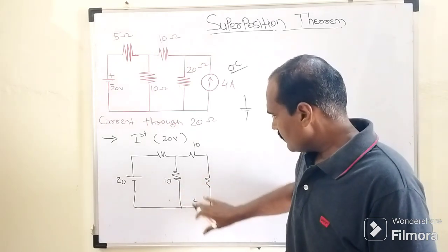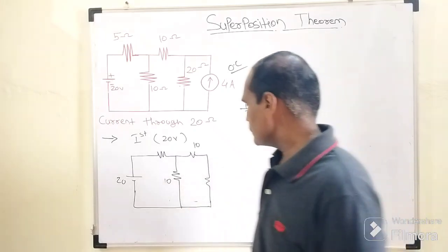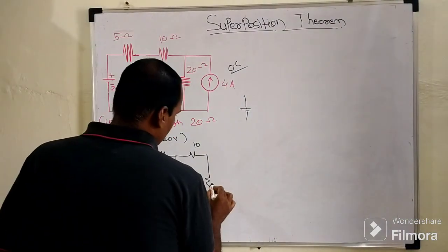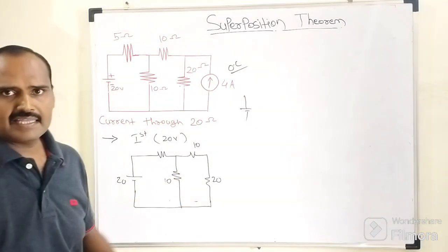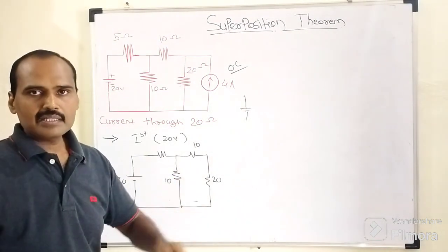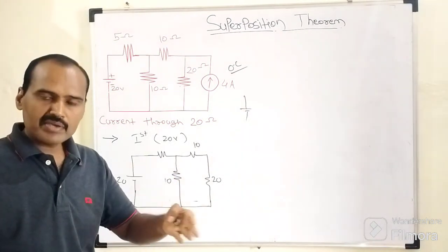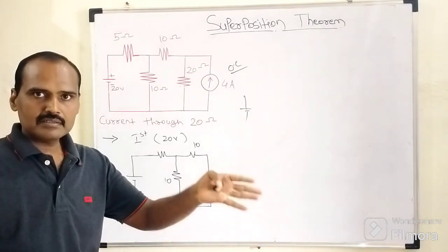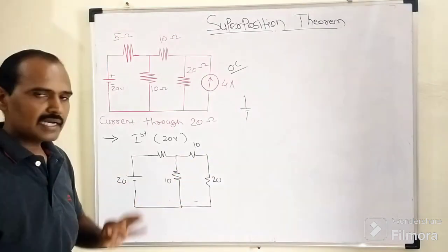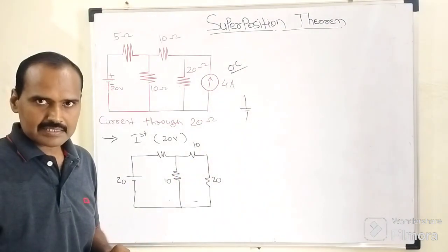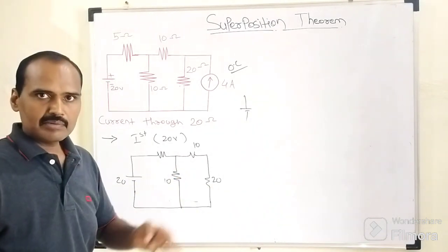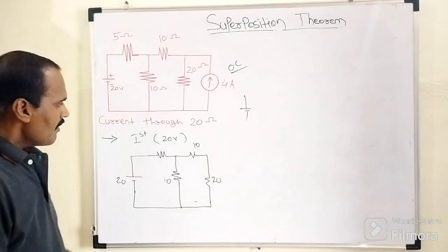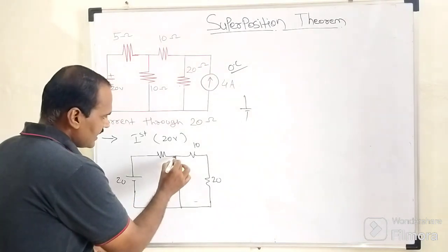So here one more thing we need to understand: why is nodal analysis most of the time preferred over the loop analysis technique? The reason behind that is each time we are reducing the number of iterations, or the number of equations is minimized in case of the nodal analysis technique as compared to loop analysis. In case of loop analysis, there will be two identical equations.